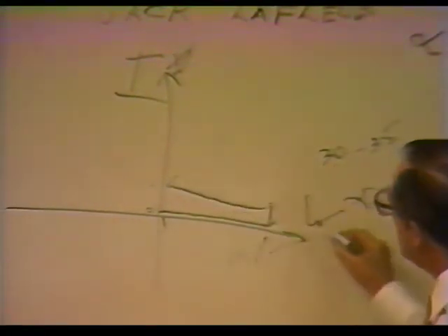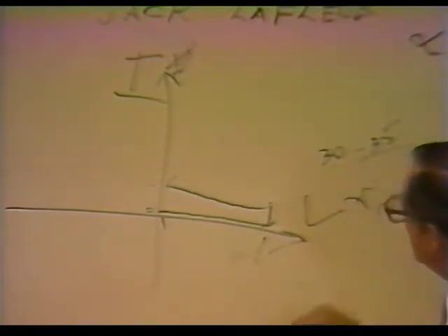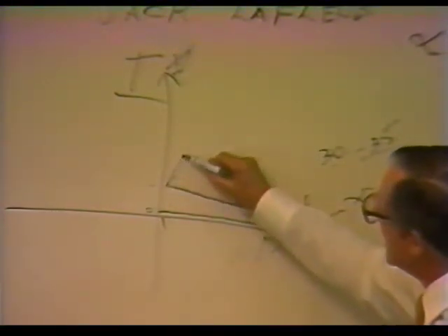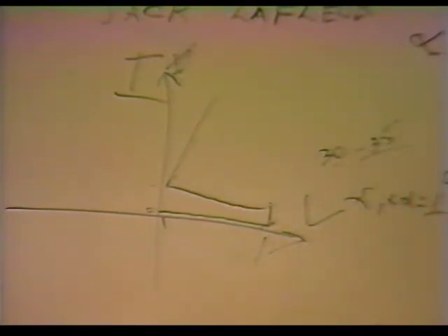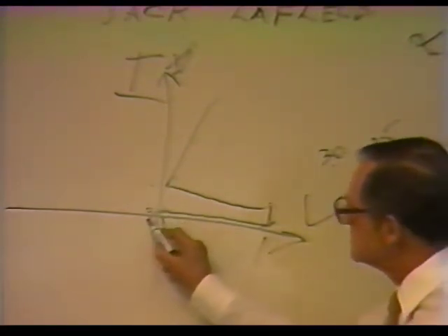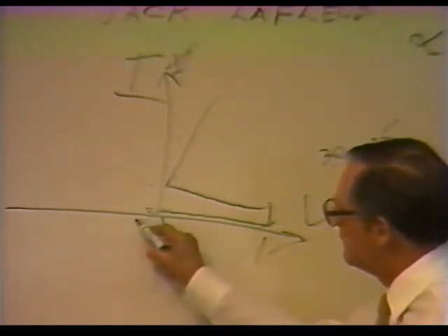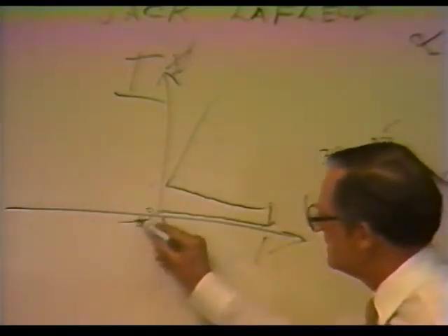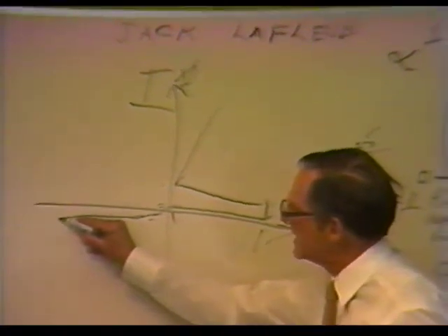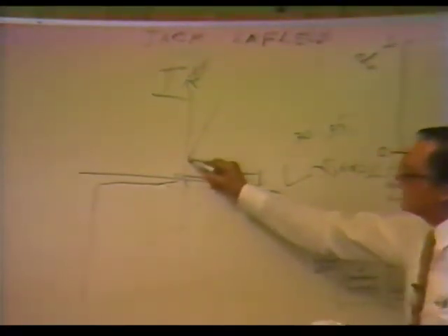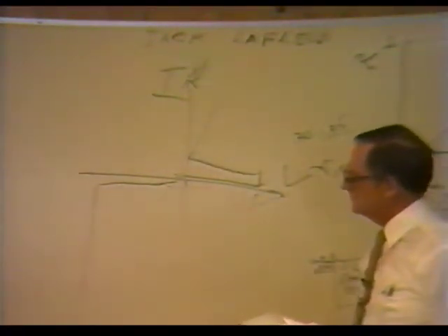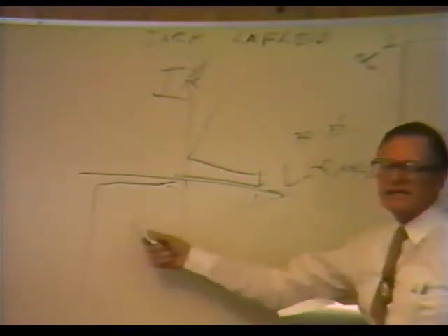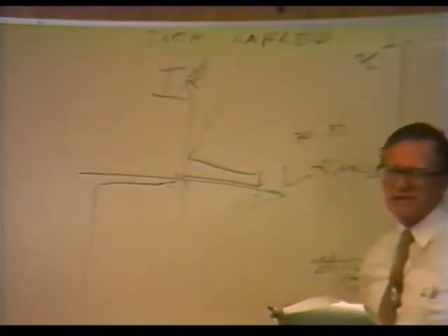Then as I crank more voltage, I will get a rise in the current. Now if I were to go in the reverse direction, that is where the cathode is positive, the anode is negative, I will go out to a place where we'll get avalanche breakdown again, but it will not go back negative because the junctions are biased wrong and they cannot sustain this feedback we talked about in the reverse direction.